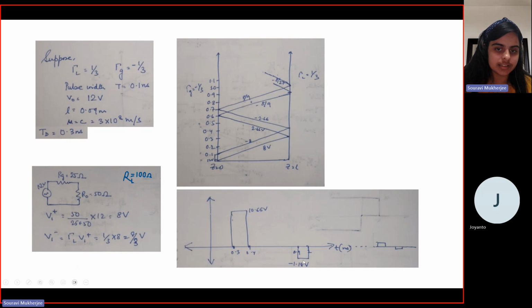the effective value now becomes negative. So what is happening is that your signal is getting attenuated. So it's not remaining the same. And why this is happening is mainly because your delay time, or the time for it to travel from the source to the load, is longer than the pulse width. If this was fast enough, then you would have got similar signals. So this kind of case where the pulse width is smaller than the time it is taking to transmit is not a good condition for proper transmission.